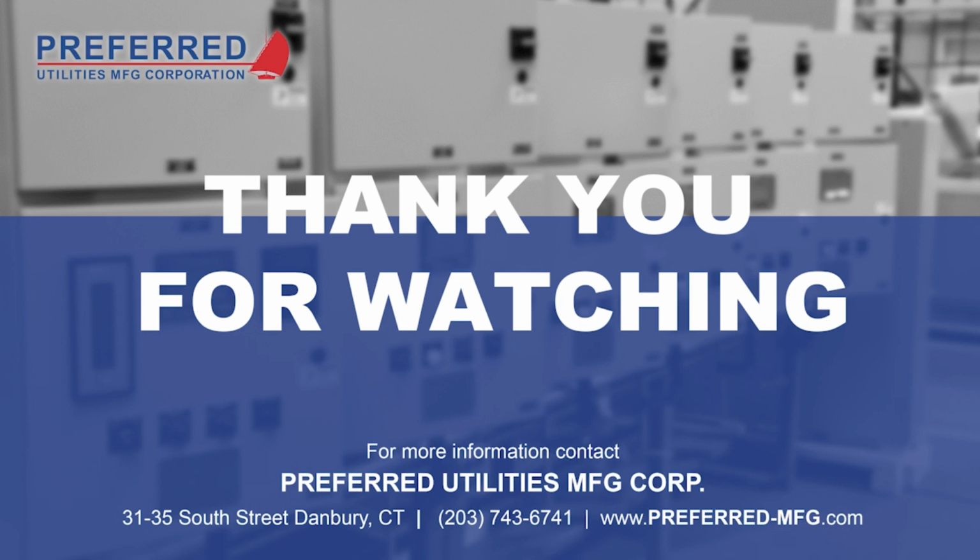That is an excellent point, and quite honestly, something I should have stressed more during the presentation. Like on flame rods, some people have issues with flame rods not detecting the flame, and because it's using the burner as the ground, on that application, if the grounds have gotten corroded or whatever, that can be the problem right there.